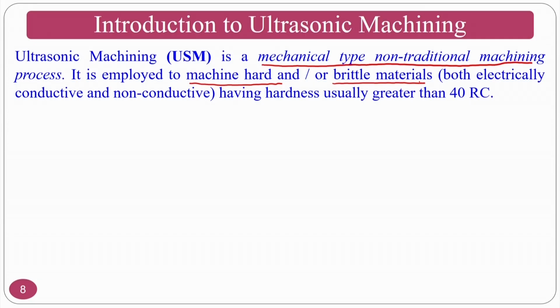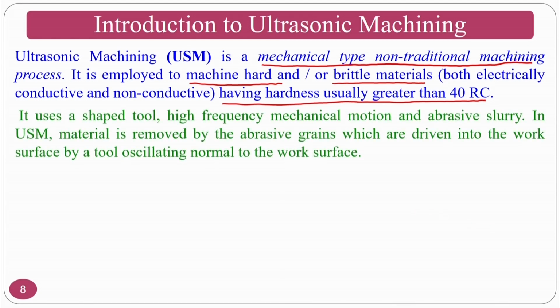Both electrically conductive or non-conductive, irrespective of that, having hardness values usually greater than 40 RC. It uses a shaped tool, basically depending on your shape. Assume that I want to get a circular hole, so you have to get a cylindrical type of shaped tool.